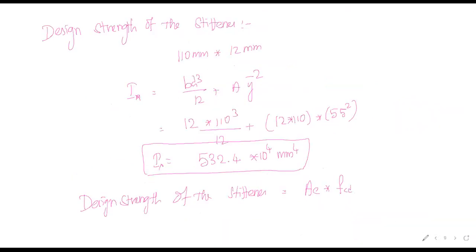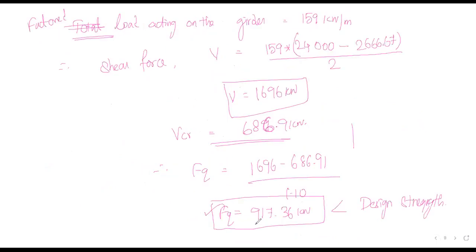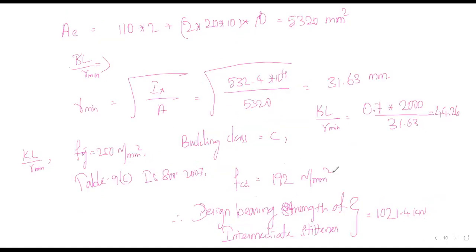But actually we are getting around 917.36 kilonewton because of the load. So it is lesser than our design strength, so definitely it can withstand. Hence the stiffener is safe in bearing transfer. Thank you.